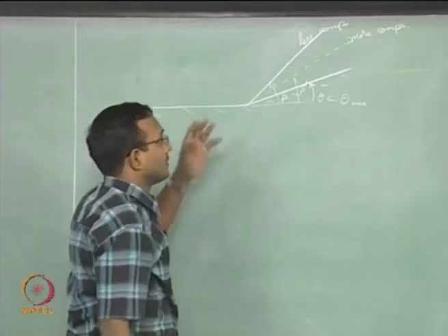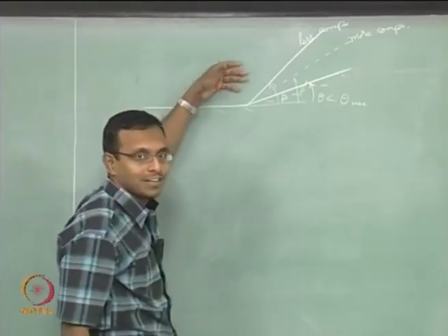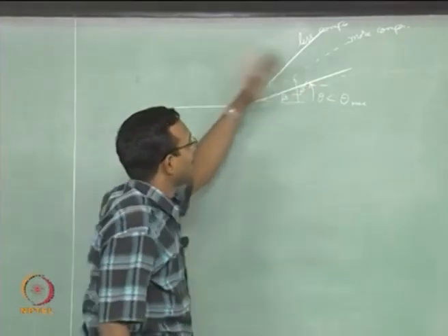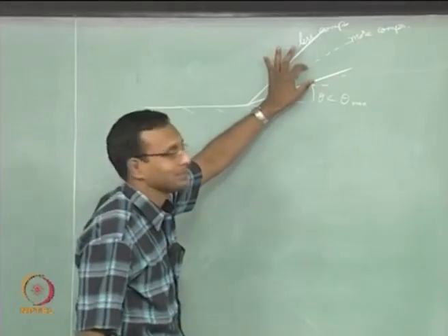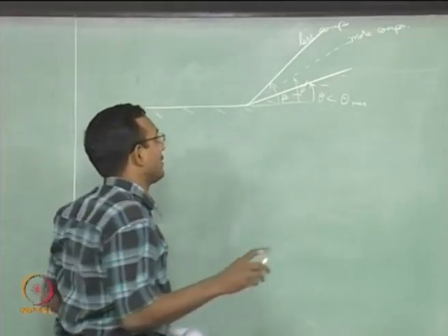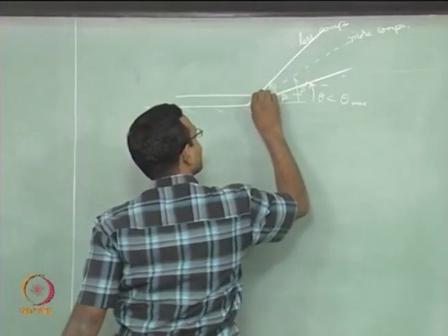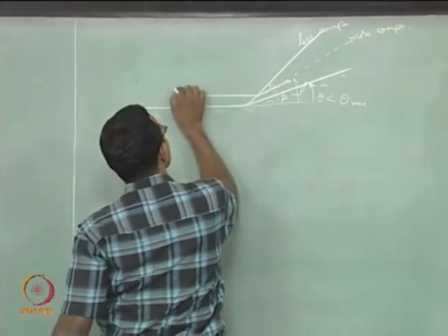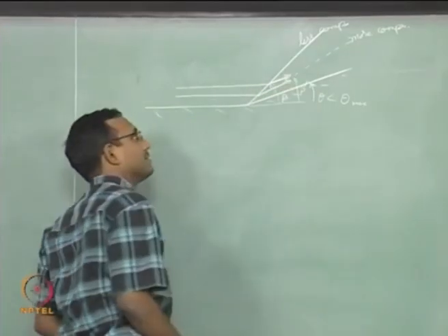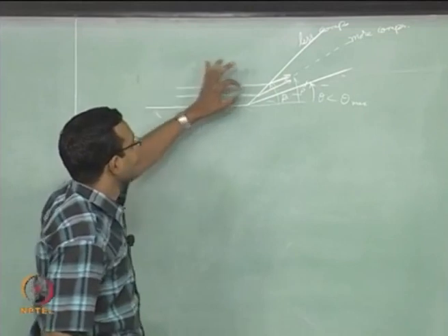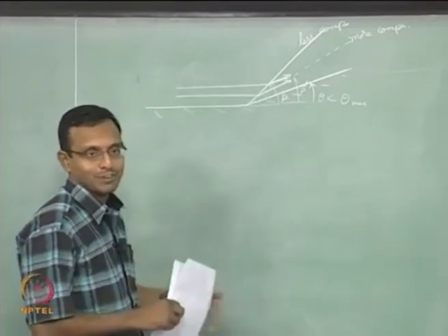Okay. Another way of looking at it, the flow incoming is so fast that if the gas is more compressible, it will compress whatever is behind the flow, behind the shock to a smaller volume. Okay. Or if I put streamlines like the way we explained things before, previously the streamlines were like this and the gap between streamlines decreased by this much, that is it is getting compressed by so much fraction.